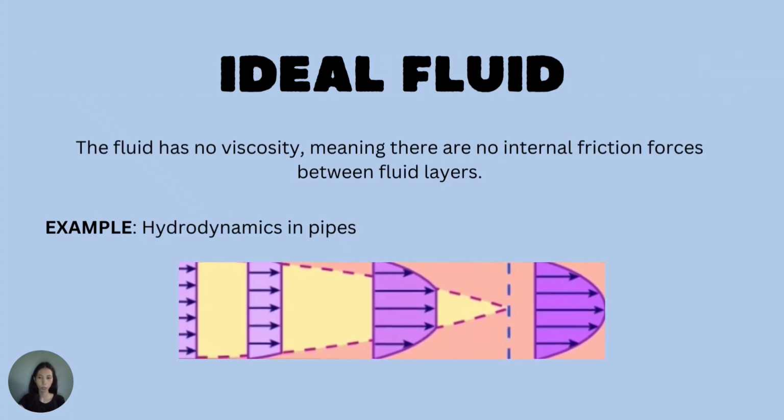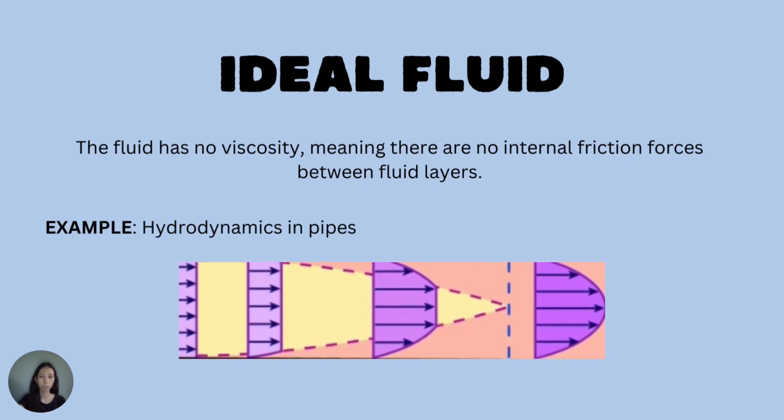For an ideal fluid, Bernoulli's equation can be applied to describe the relationship between the pressure, velocity, and elevation along a streamline. It states that in a steady ideal fluid flow, the sum of the pressure energy, kinetic energy, and potential energy per unit volume is constant along any streamline. This equation is foundational in fluid mechanics and is used to analyze the behavior of fluids in various practical and theoretical scenarios, providing insights into fluid dynamics and engineering applications.